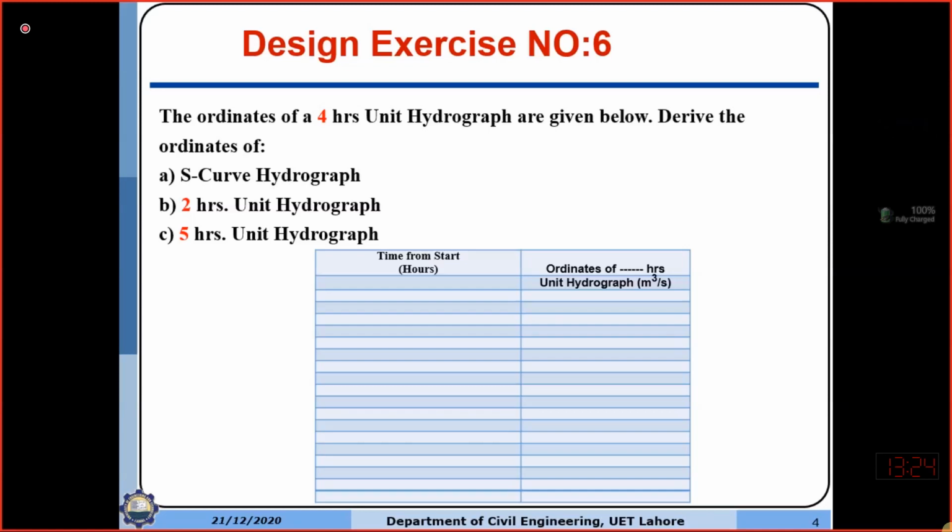So it's a lengthy process. It involves expenses, it involves time, it involves previous data records to be obtained. So once you make the hydrograph of certain duration for a certain area, you can use that to find the hydrograph of any other precipitation having the same duration as the unit hydrograph.